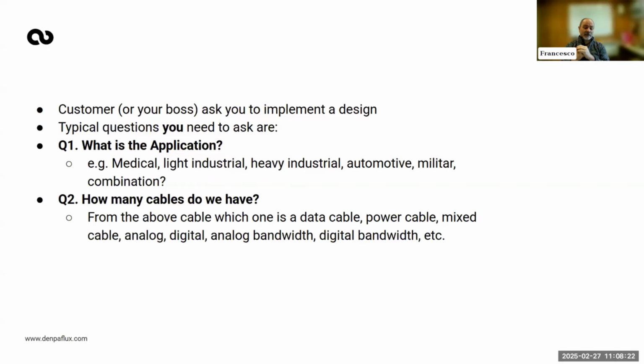Just to give you an example, if you are designing something for automotive, some of the automotive tests, the radiated immunity for example, subject your electronics to a field of up to 80 volts per meter. 80 volts per meter is a lot.